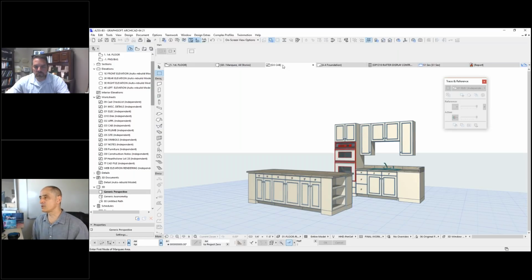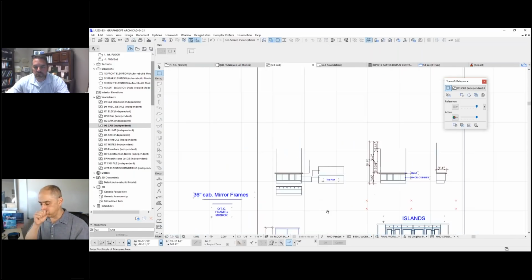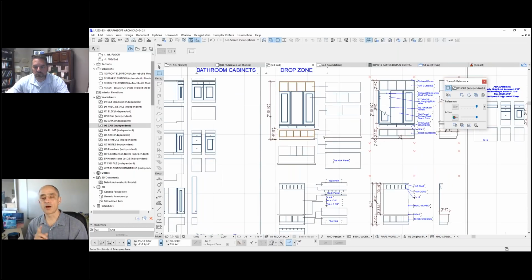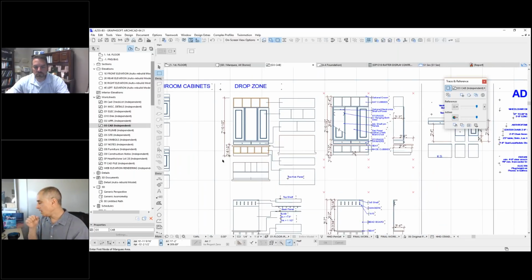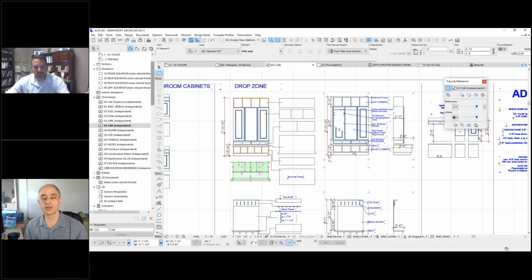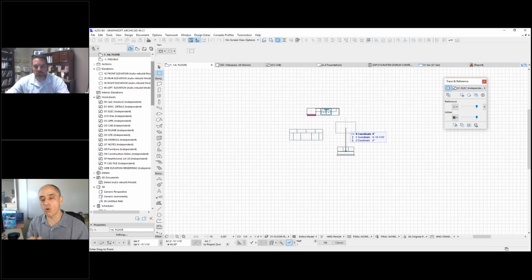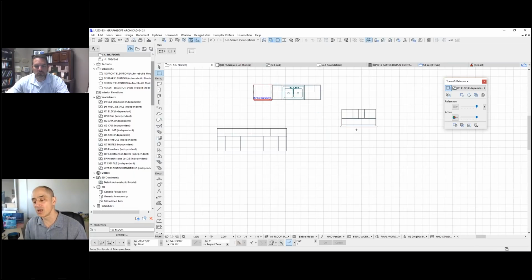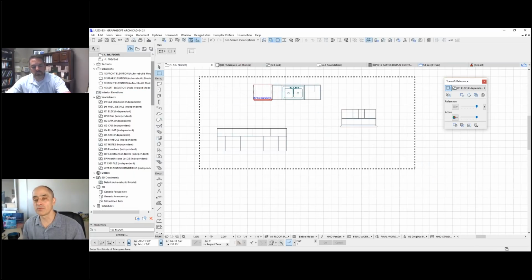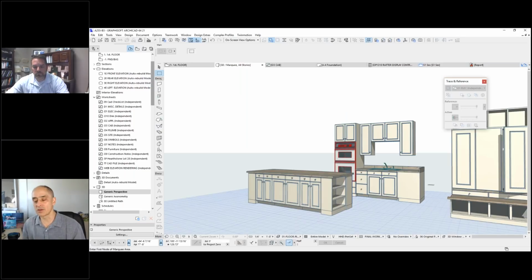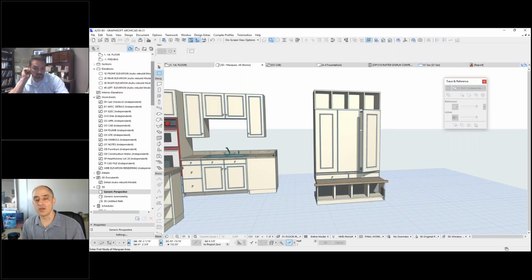So just to re-emphasize what Chip said, you can eyedrop individual elements, and then you've set the tool, the object tool in this case, to be ready to place one or possibly more than one of those elements. If you want to get a group of them, like that set of cabinets for the island, then you need to be in the worksheet or in whatever view has them and select them, copy it, and paste it.